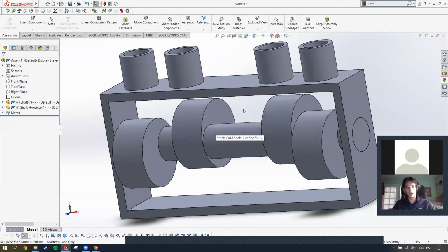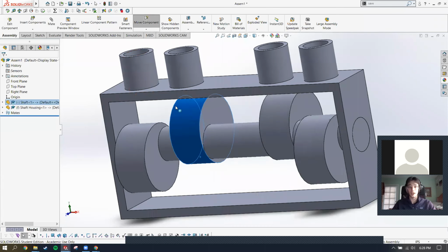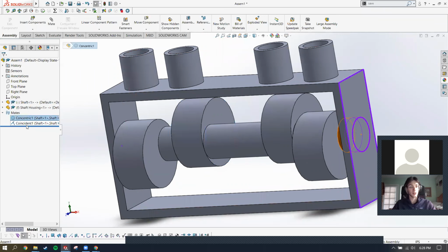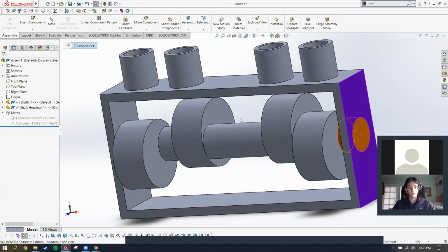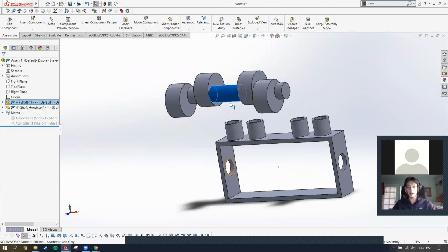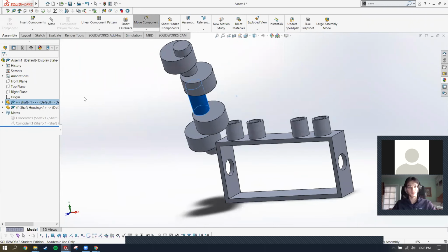And the next thing I'm going to talk about is design verification in assemblies. There's this tool called the Move Component tool. You can click and drag, first of all, to move components around, assuming they're not fixed, or you can hold right-click to rotate components. Bad example because the mate is currently held in place. But if I have this component free, if I hold right-click, it'll rotate the component in place. Left-click will slide it in place.